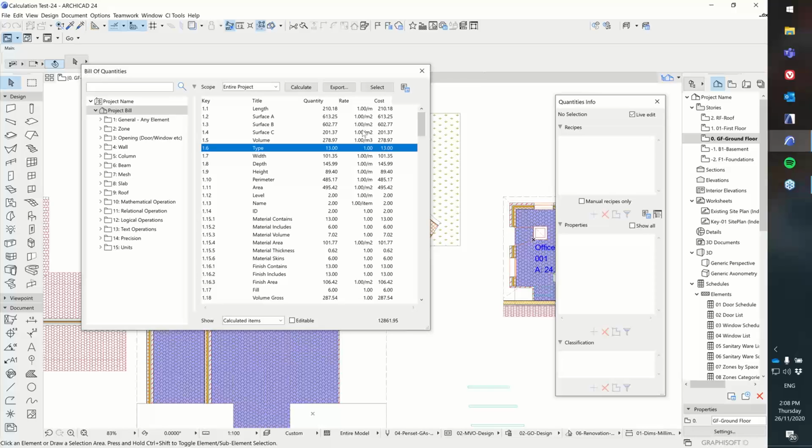because we have not assigned any costing information to our bill of quantities. And this may not be something that you even want to do. If all you're interested in doing with the tool is producing actual measurements and numbers, or literally just quantities out of it, then you can just do exactly what we've done in this example and ignore it entirely. Everything has a quantity at a rate of 1, so its cost and its quantity will be the same, and you can essentially just ignore this cost section here.